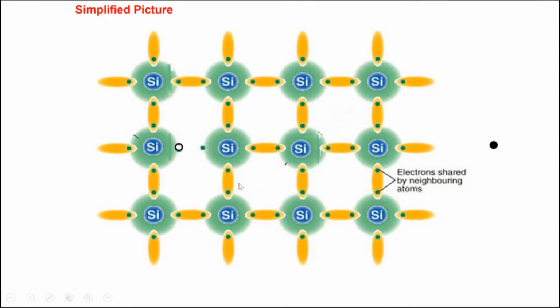The electron moves and then gets scattered, and it's moving in some random directions here. Scattering occurs because in a crystal at room temperature, the silicon atoms that you see here are not in their equilibrium position. The silicon atoms are vibrating, and these vibrations are what causes the electrons to scatter. So an electron may start at a place and doesn't continue to move in a straight line, but it gets scattered due to the vibrations here.